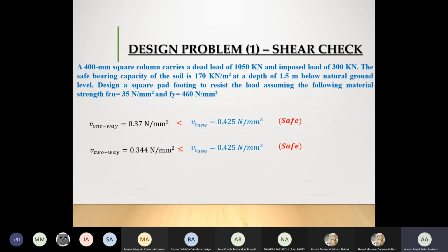Now returning back to our problem, if it fails in shear. The main failure in a foundation is normally shear, because it will not deflect. If it came in your midterm examination, and your foundation has failed in shear, what will you do? Increase the depth. So we can say that by increasing the depth, we are going to resist, or somehow stop the shear, or reduce the effect of shear. The same example of the books: if I keep 2 books on one side, and on the other side I have 10 books, and I try to cut them with a knife, which one is going to be harder for me to shear, or to cut fully? Which one?